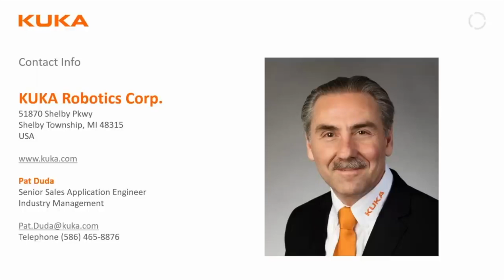Can you clarify how you connect sensors to the KUKA field bus? Okay. We have a software called Work Visual, which you could think of as like the Visual Studio for KUKA robots. Part of the setup of a KUKA robot uses Work Visual to set up and define your field bus.